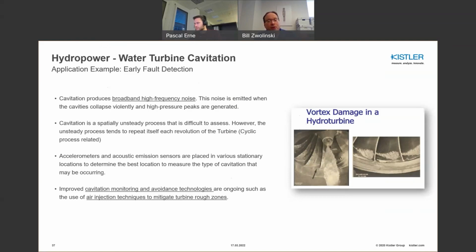And certainly part of the investigation with the USBR was they were looking at ways of injecting air or changing flow in terms of mitigating some of the cavitation environments. And that's really a pragmatic approach, because if you could mitigate that without losing, say, the ability to generate power, then you have a viable means to extend the life of your rotating equipment.